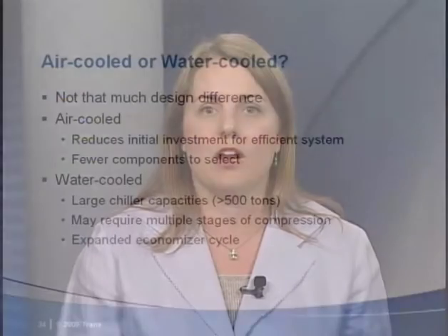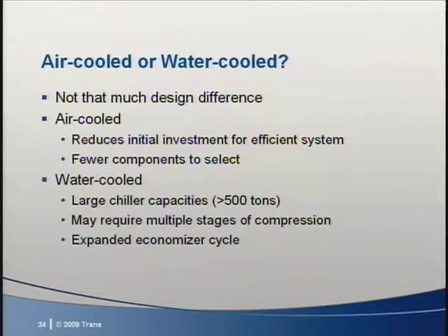We're making this choice so that we can drill down to a deeper level of detail and get as specific as we can, while still addressing issues that virtually all ice storage projects face. Air-cooled systems have a lower initial investment, and they can offer the efficiency of a centrifugal chiller without ice storage. Water-cooled chillers can be larger for economies of scale on larger projects.